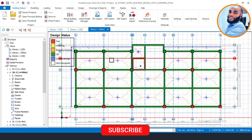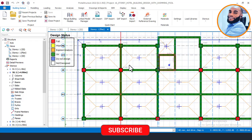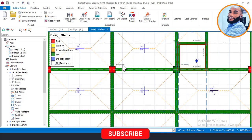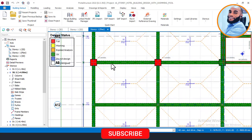Right now, let us start by checking the columns. Why are the columns failing? Most of the columns are showing green and some are showing red. These red ones are the ones that fail. So let's begin to check on the columns to see why they are failing.